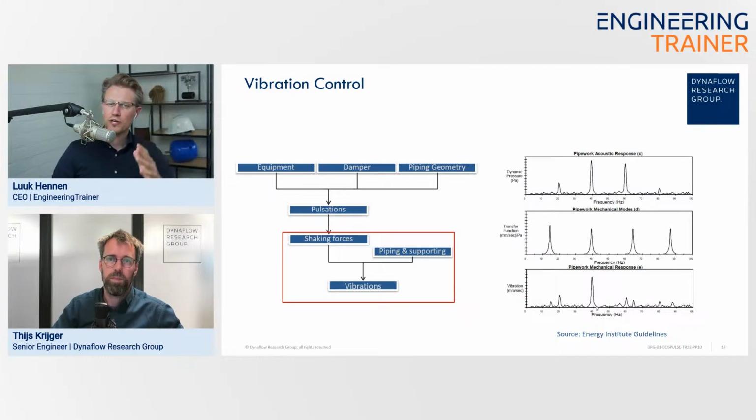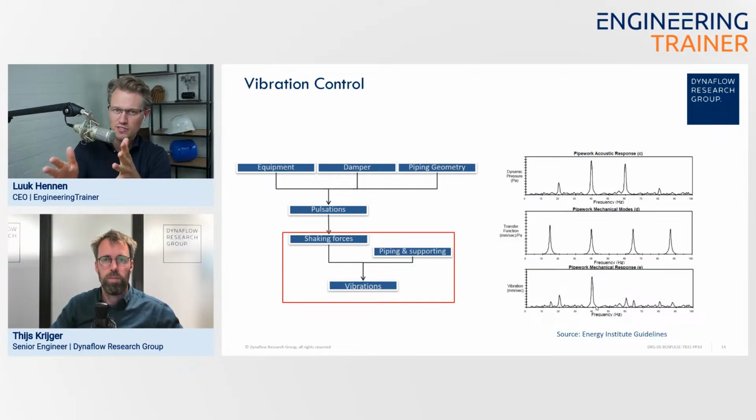So if I summarize it correctly, you have the reciprocating compressor causing pulsations, then there might be acoustic resonance, and then you get your pressure pulsations in the actual system, and those can cause mechanical resonance, yes or no. Let's say you have a very stiff system, so no significant mechanical movements, whether we have resonance, yes or no. But you have really high pulsations. Is that a problem?